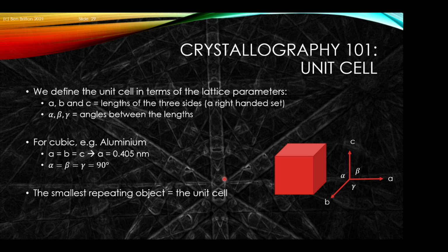And we can describe the motif of atoms that are present within that unit cell, i.e. with respect to this cube, in the FCC structure, there is an atom at 0, 0, 0, and there are atoms located in each of the faces. So 0, a half, a half; a half, 0, a half; and the third, I think, is at a half, a half, 0. So that is the 3 face centers, and then there is the fourth, of course, which is on the vertex.